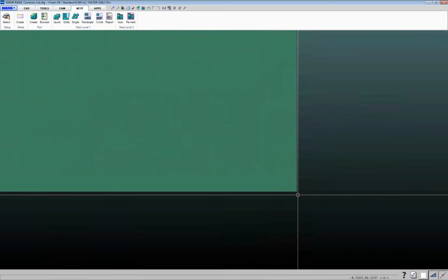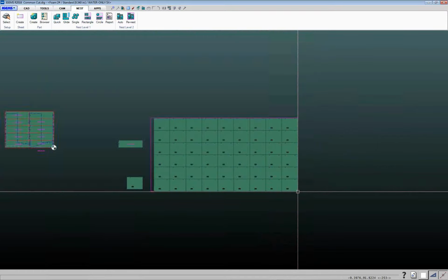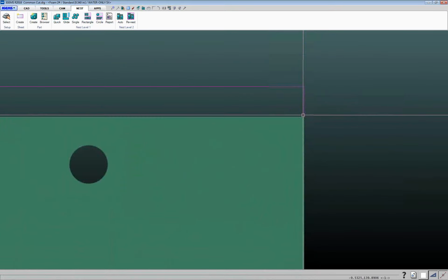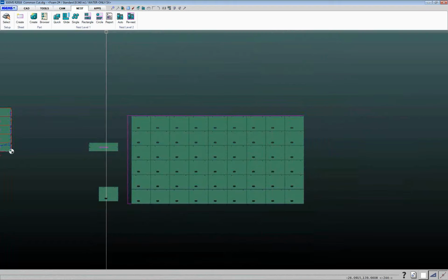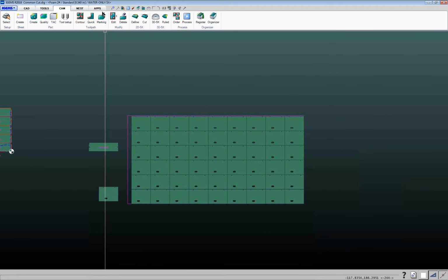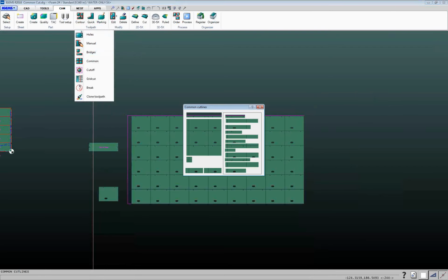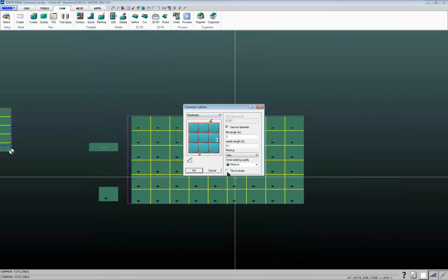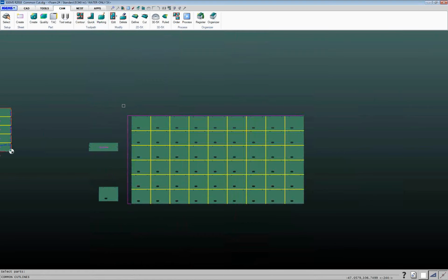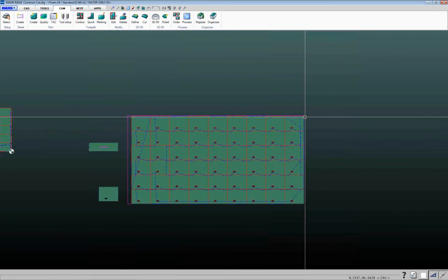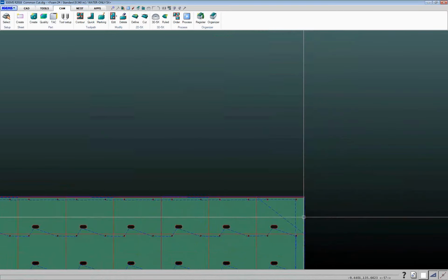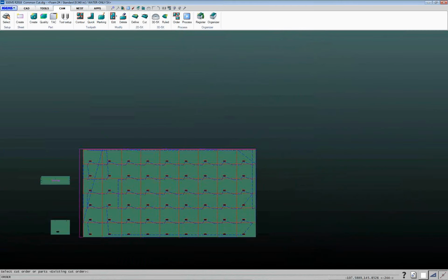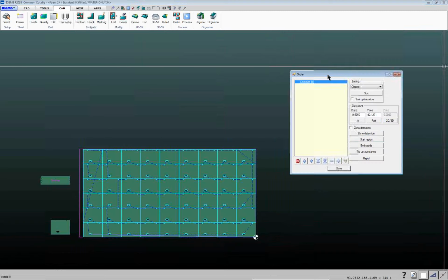to my common cutting, what I'm going to do on this one is the trim to sheet option. So I've set my sheet border to 0. So it's put those parts right up against the edge of the sheet. So as long as I can accurately position the sheet on the table with a fixture, or my tolerances are loose enough that it'll allow, I can come in here, and when I do the common, I'm doing my sheet-wise. If I choose the trim to sheet option and click on OK, drag a box around this, it's not going to do those cuts along the edge of the sheet. It'll just use that raw edge of the sheet for those edges. So this can be, again, a big time saver if your tolerances can allow it.